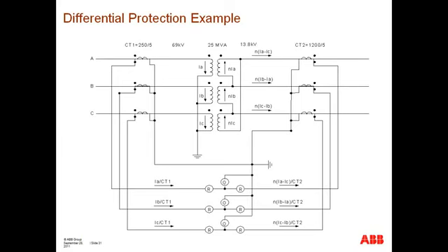If there are any deviations from that, you have to take into consideration that you don't have electrical coupling from high side to low side. What I mean by that is you cannot expect to apply Kirchhoff's law from one winding over to the other winding and expect that the current that flows on one winding equals the current that flows on the other winding multiplied by the turns ratio. You need to take into consideration that there are losses involved.